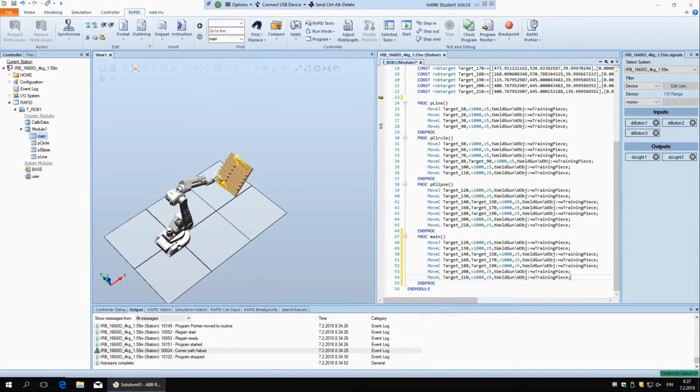And a little bit about what this code here means. So the first one here, I think you can guess what it is. Move is just the move command, and then you have J, L, or C: joint, linear, or circular. For joint and linear you have only 1 point, but for circular you have 2 points, because the first one is a point that is somewhere on this circle or arc, and then the second one is the end of the arc, and the previous one is the beginning.